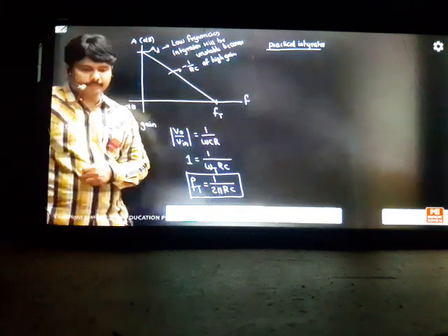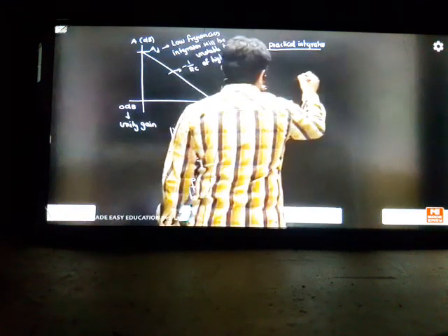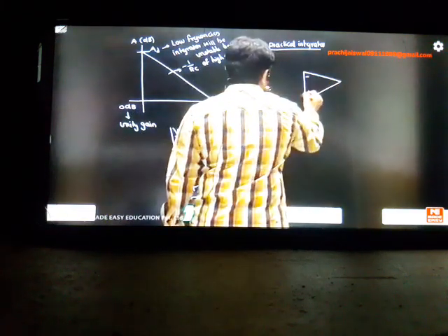But you are going to saturation. It's not meant that the device will be damaged, but you are going into the non-linear region. So a practical integrator should not go into the non-linear region. Then how do I design it? We'll take the minus and plus inputs here.